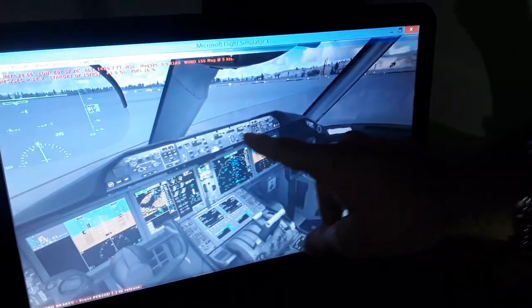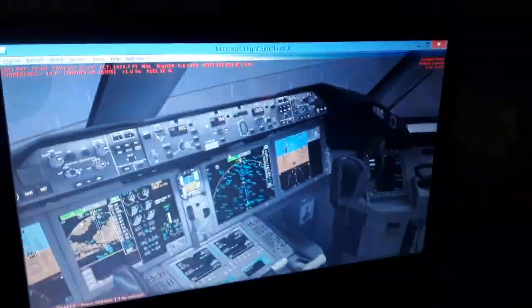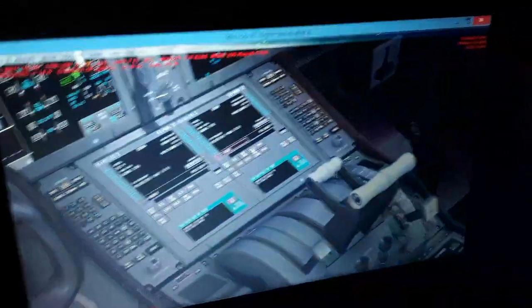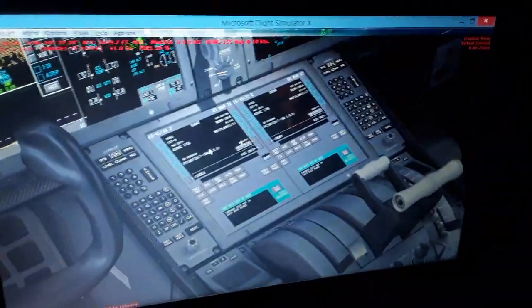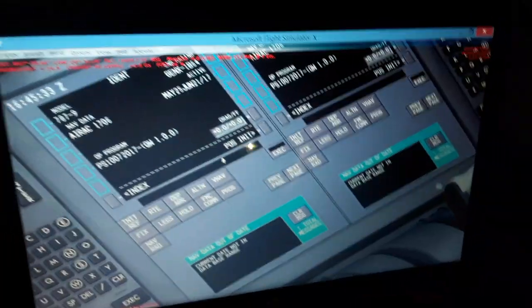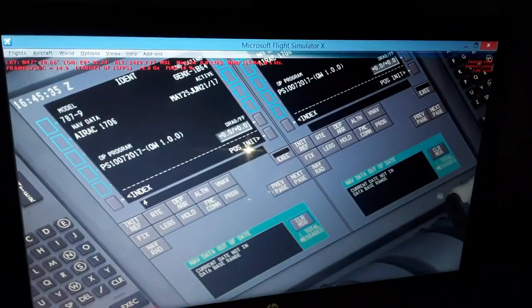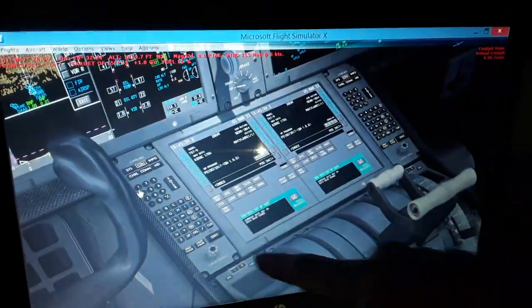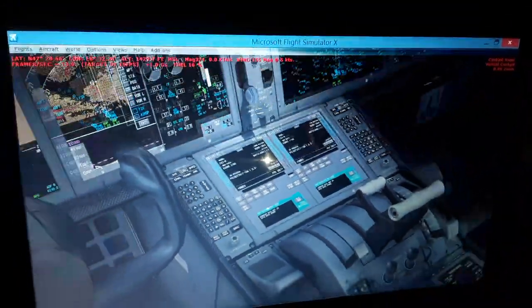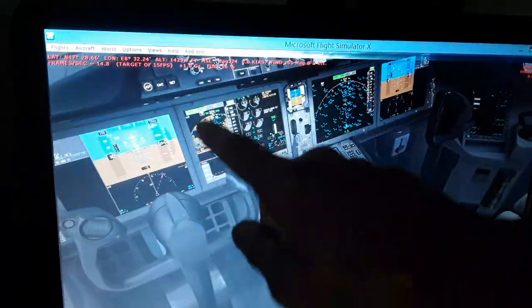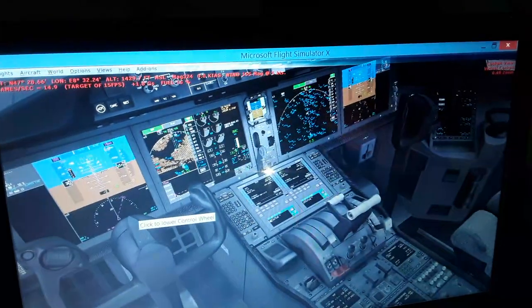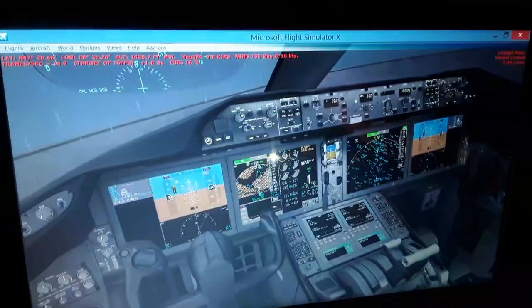It's gonna be used also from the autopilot flight director system panel. When we connect the autopilot flight director system panel, it's gonna follow the flight plan I'm gonna create here in the flight management computer. So you will see later how I'm gonna use this flight management computer input from the keyboard and use the mouse pad also. The data we need is going to be displayed here in the navigation display, the horizontal and vertical profile. Also in the HSI you're going to see the flight plan we're going to create.